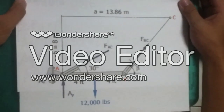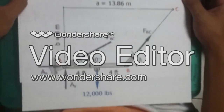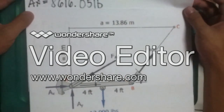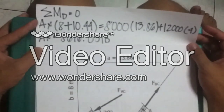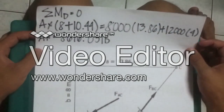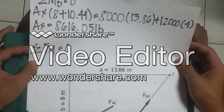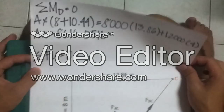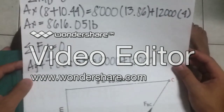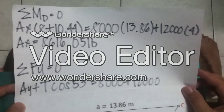To find the reaction at point A, first, summation of moment at D is equal to 0. Then AX times 8 plus 10.44 is equal to 8,000 times 13.86 plus 12,000 times 4, and AX is equal to 8,616.05 pounds. To compute the AY, we use the summation of Fy is equal to 0. Then AY plus T cosine 53 degrees is equal to 8,000 plus 12,000.